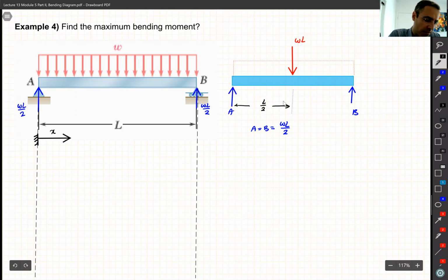And the good thing is only one section is going to solve my problem, right? Because I have only one region. So I draw the free body diagram for one section, like that. I put the loads. Now this distributed load over here is not the whole thing.